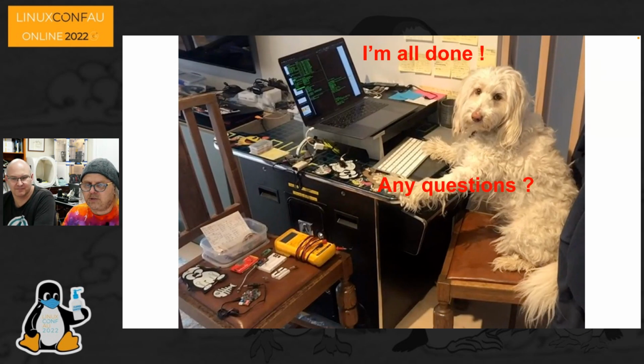The audio codec is a little bit more complex to control. It's still going through that, but it takes a series of I2C commands to set up the inputs, the outputs, the clock rates for the I2S bus and so on. But that is all just C code that we're changing on top of the FPGA.